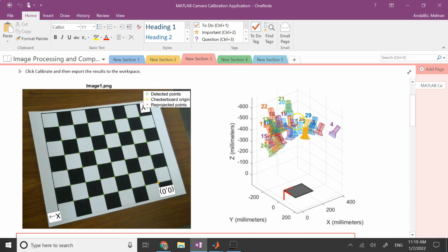Okay, you should not keep taking pictures at the same location and orientation all the time. Otherwise, those pictures all look the same and they are not any useful. The important thing is to make sure those pictures really only contain your chessboard pattern and not a lot of background. Otherwise, later you have to crop them and process them, and MATLAB is going to have a hard time basically using those. So let me show you what I mean.